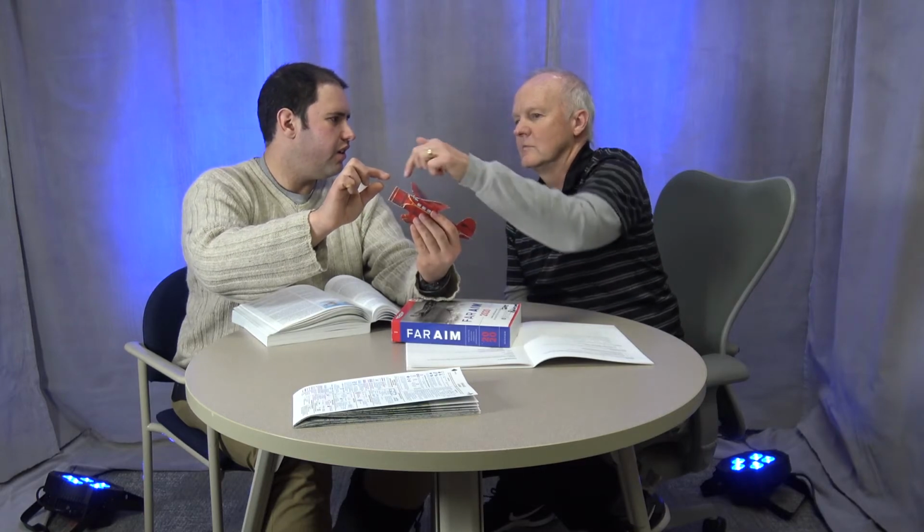So the blade has more angle of attack, and therefore more lift on the right side, and the blade on the left side is moving up. It has less angle, less relative speed as well because of the relative wind,